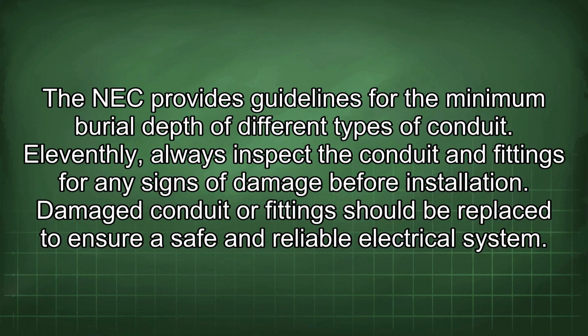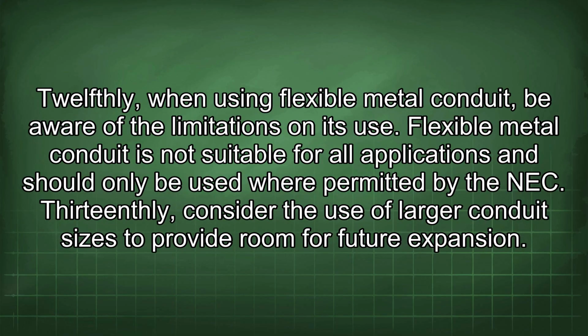Eleventhly, always inspect the conduit and fittings for any signs of damage before installation. Damaged conduit or fittings should be replaced to ensure a safe and reliable electrical system. Twelfthly, when using flexible metal conduit, be aware of the limitations on its use.